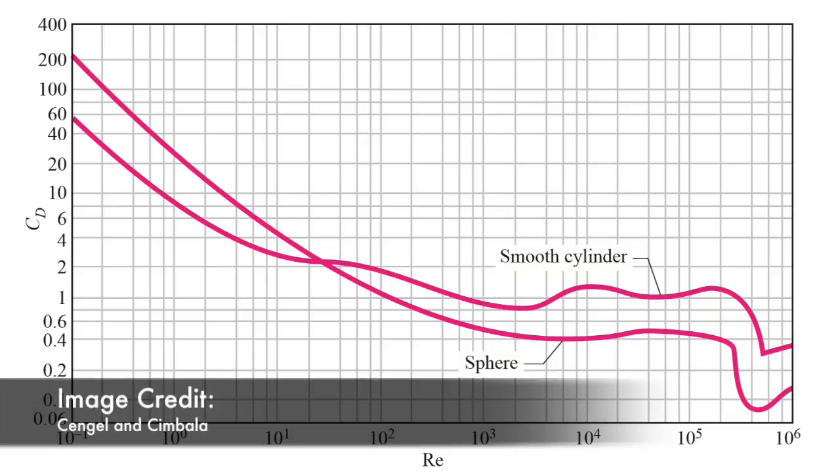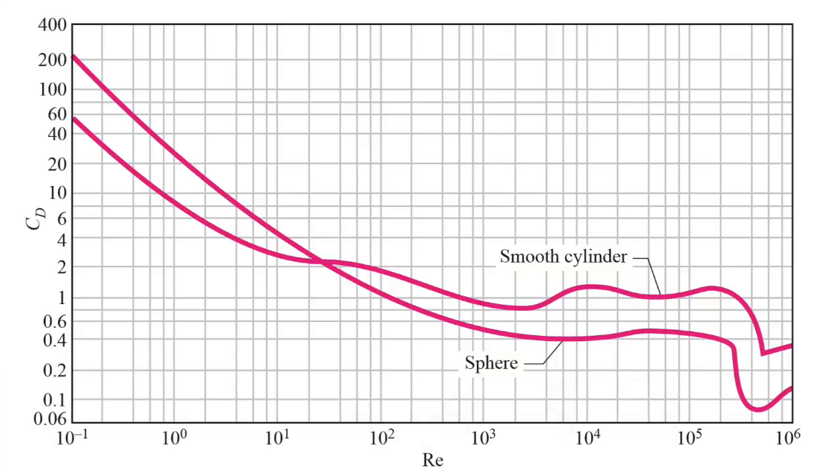To calculate friction drag, each panel was considered as a flat plate with a unique Reynolds number, and tangential velocity was calculated at each pressure tap based on the dynamic pressure. The friction drag coefficient for each panel was then calculated and used to find the total drag on the cylinder, which then was used to find the total drag coefficient. The overall drag coefficient in the baseline configuration, taking into account both friction drag and pressure drag, was around 0.57 for the three speeds, and in the trip configuration the drag coefficient was around 0.62.